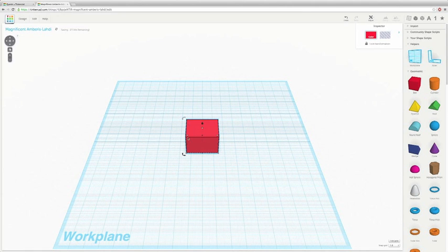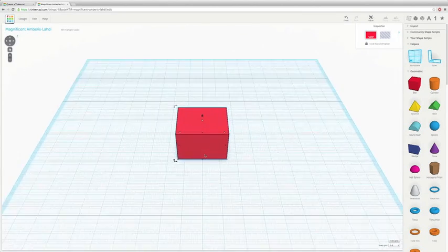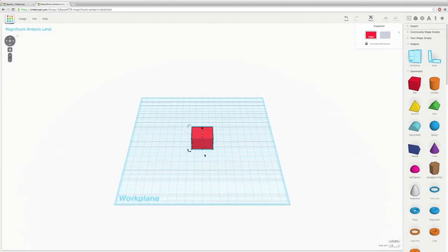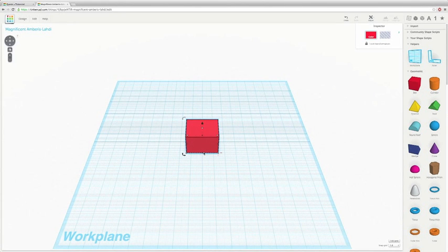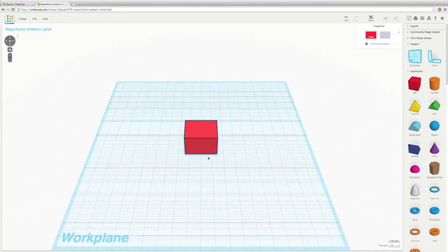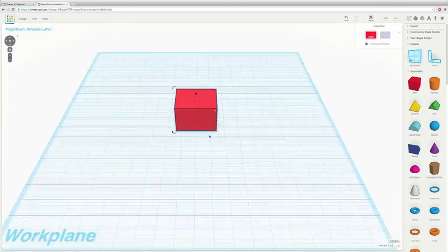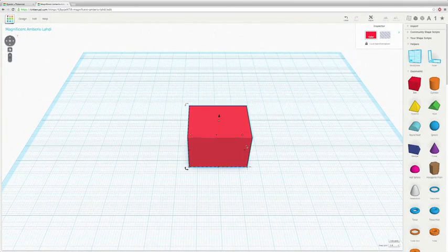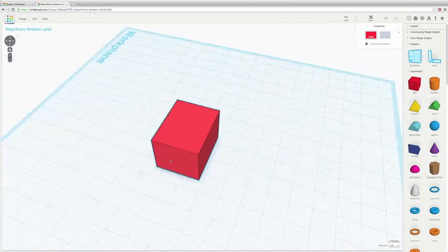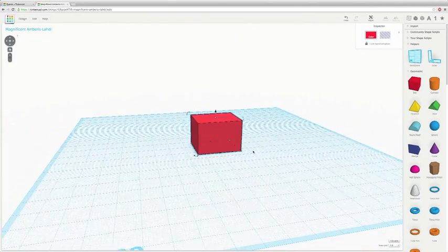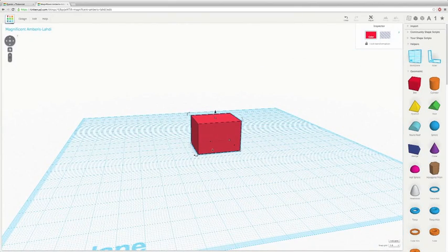Alright, so let's learn some quick ways to move around the object. So if I click off, I can click back on. That's left mouse click. If I scroll the scroll wheel, if you have a 3-button mouse, you can zoom in. Scroll out. Alright, great. If you press down on the scroll wheel, you can pan around the object. Alright, so scroll in, scroll out, pan around, and then last, right-clicking will let you orbit around the object. Alright, so I don't use this top left corner at all. I just use the mouse.